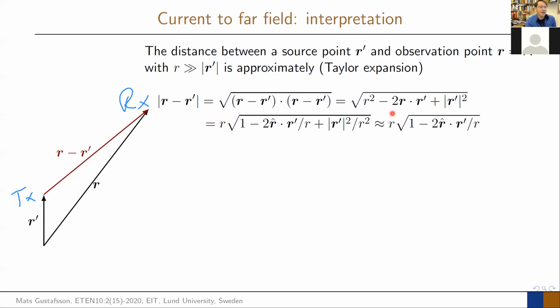And then we say that we are far away from our antenna. What does that mean in practice? This is my antenna that sits here. Think again of this dipole. It is a few centimeters long, and you are like 100 meters away from it. So this dimension of the dipole is very small compared to the distance you are away from it. That was precisely the formula we had for this far field distance. You have to be far away in these cases.